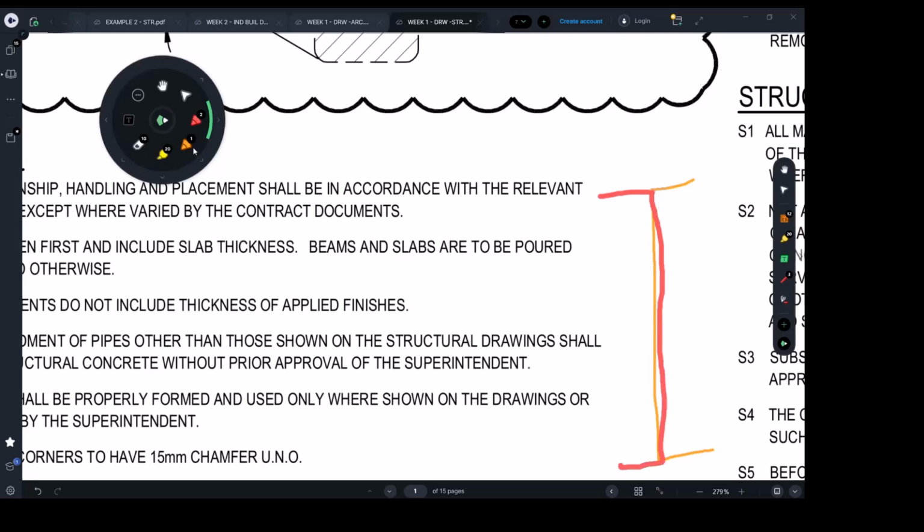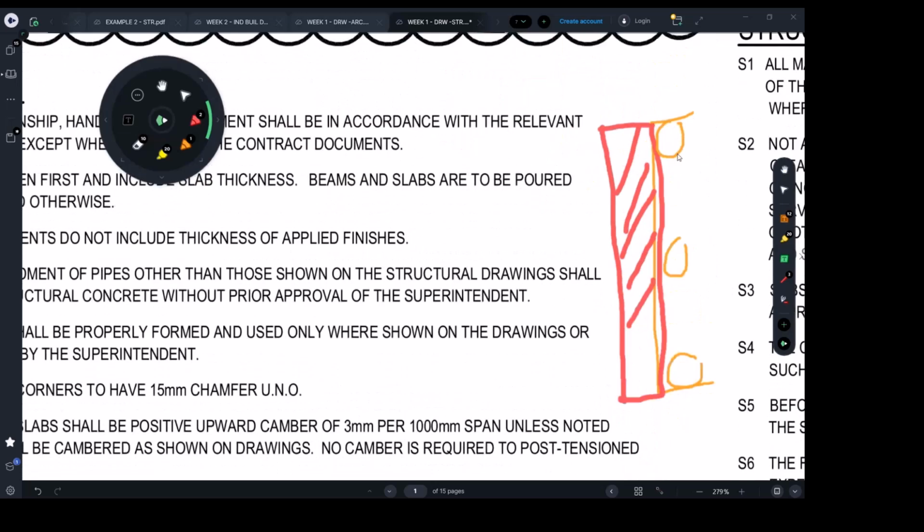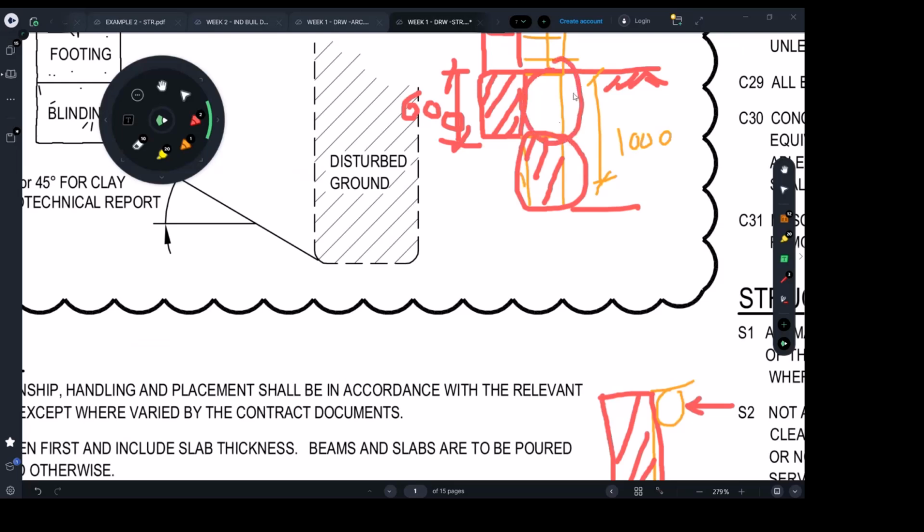neighbor's. Okay, so what I mean with bored piers is we're going to be putting a bored pier every 2 meters, because when you excavate for a bored pier, you won't really disturb or impact the neighbor's footing, the red one here, because you're making a hole every 2 meters. So really, it's not a problem. You won't really stress out the soil. Okay, so these elements I'm showing you, the ones I'm hatching with red, are circular bored piers. They're going to be deepened to wherever the soil engineer wants, and you're going to be placing them wherever is safe for the neighbor. And who says that to you? The structural and the geotech engineer. We place them apart from each other to not stress out the existing footing. And then on top of them, we're going to be building a shallower strip footing with adequate reinforcement to act as a beam. And that's the solution here.